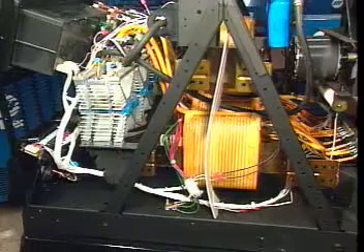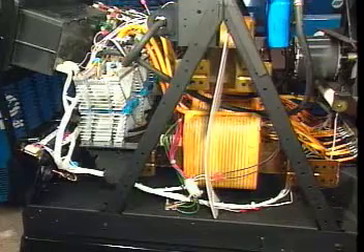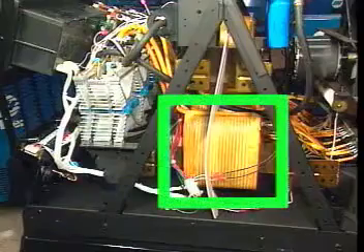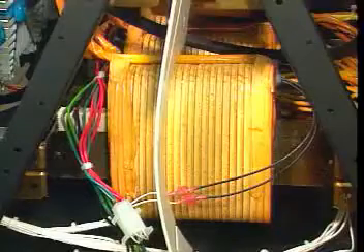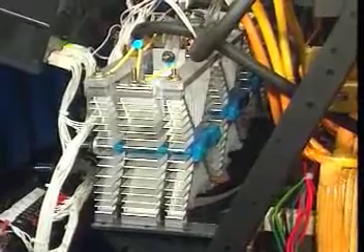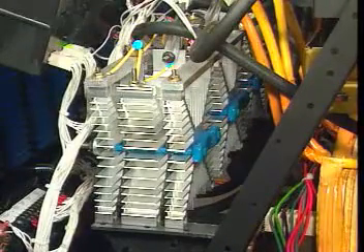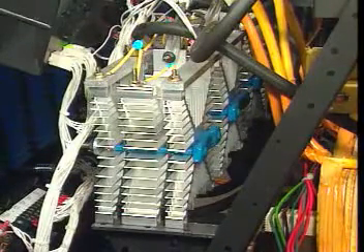While electric motors were once used for this conversion, modern welding machines use transformers to produce AC welding current. To also produce a DC welding current, the transformer's output is connected to a rectifier. A rectifier is a device that changes alternating current to direct current.